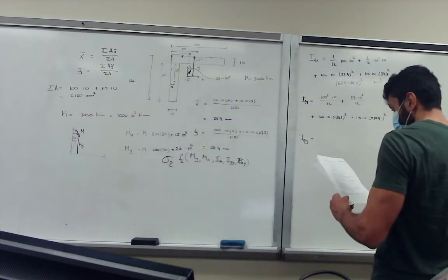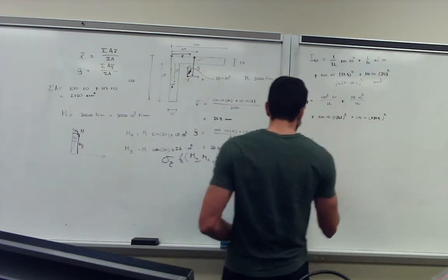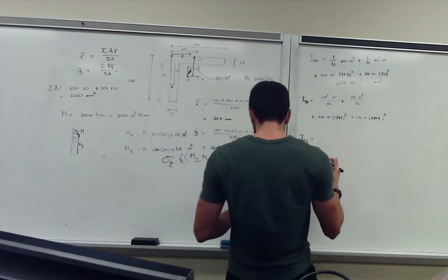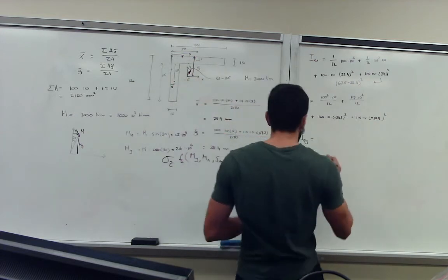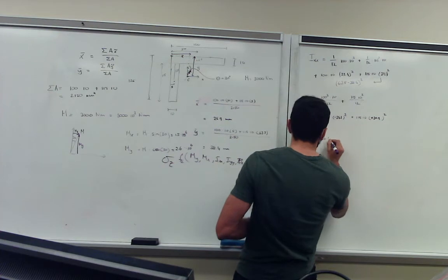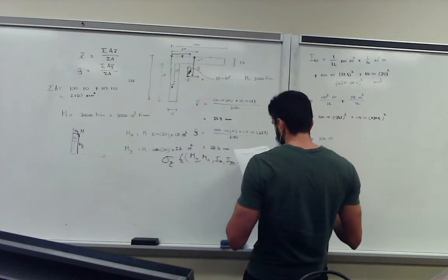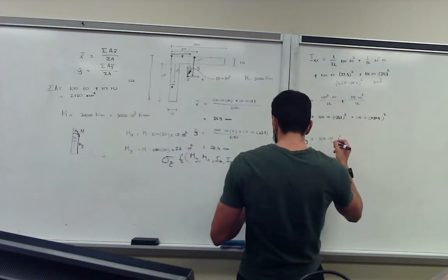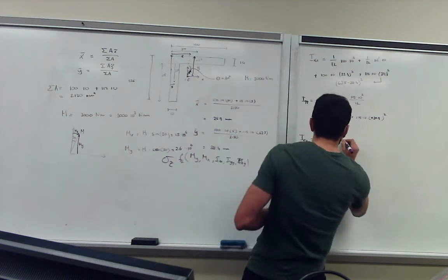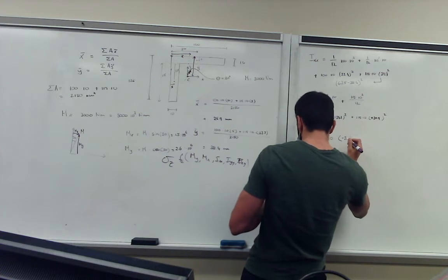And in that case, it's just basically the area times the shifting of the centroidal axis. So in this case, 100 times 10, and then we have to shift with x and y. So we shift in x, we said that's 24.1. Explain the 24.1.